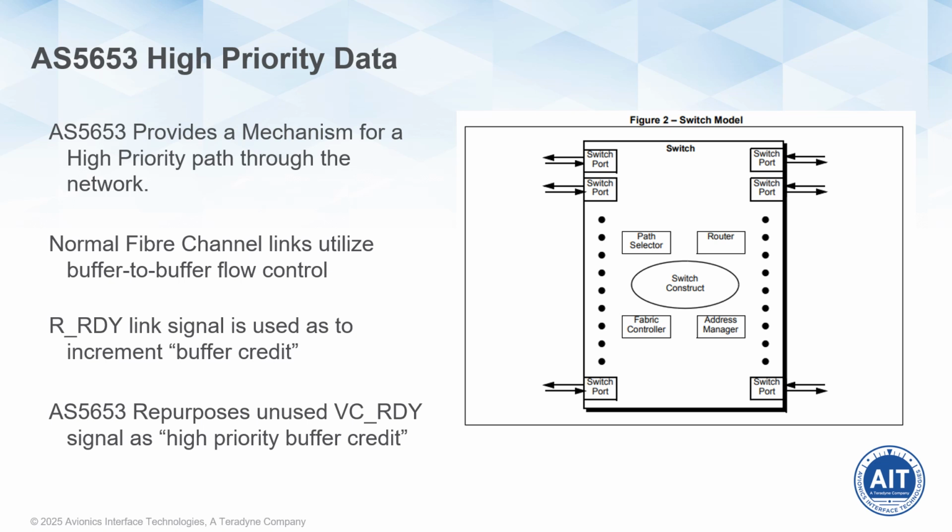In a typical high bandwidth application, there's generally going to be a producer of the high bandwidth traffic and then a consumer or multiple consumers of its data. It's likely even that each link in the path from the producer to the consumer or consumers will become saturated. Each buffer in the switch ports and the node ports is going to be filled, just waiting for some system driver to handle their incoming data.